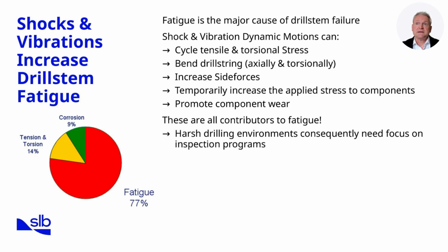For these reasons, harsh drilling environments where shocks and vibrations are common require proactive inspection programs. By regularly checking for fatigue cracks or early wear, operators can remove compromised components before failure occurs. In summary, vibration doesn't just reduce efficiency, it directly shortens drill string life. That is why fatigue management must remain a key focus of drilling optimization. Next, we'll summarize the overall impact of shocks and vibrations on drilling performance.